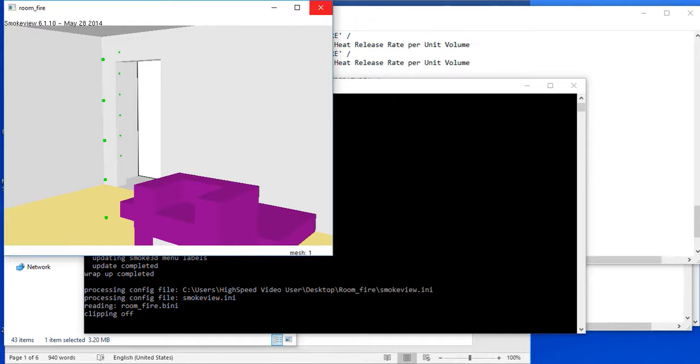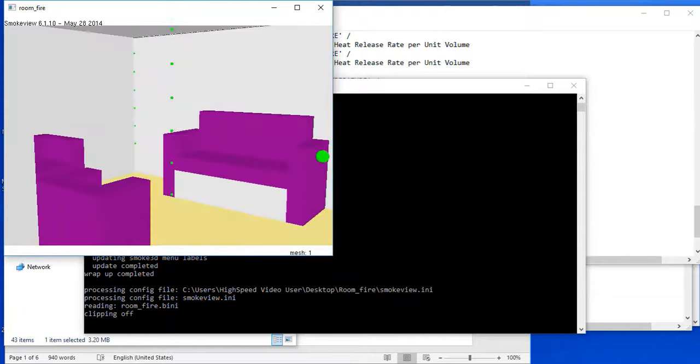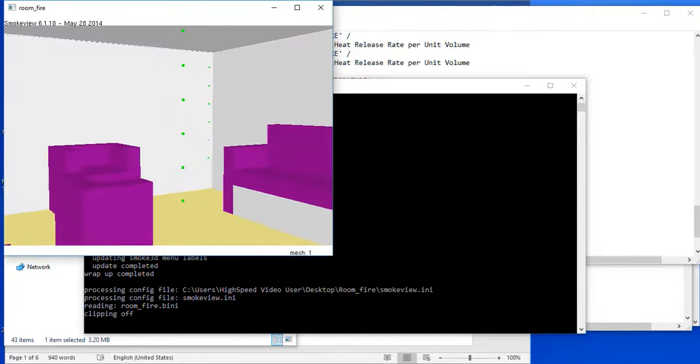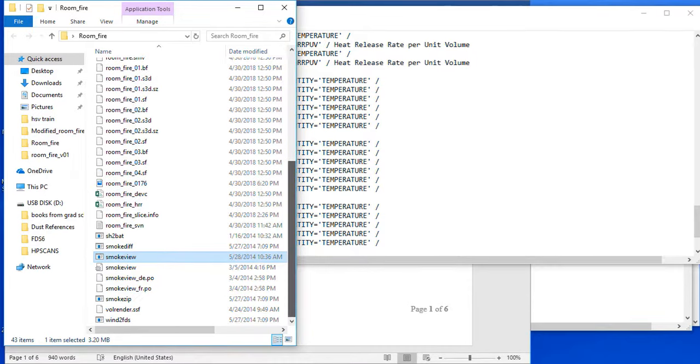So I used to assign a project where we had thermocouple tree data and a room fire and have people try to model it using the Nuclear Regulatory Commission's FDTs, the Fire Dynamics Tools, CFAST, and FDS, and compare what the students could get out of the different ways of modeling, the different levels of modeling, from a spreadsheet to a zone model to a field model, and write a report on the ease of use versus the data that you get out of it versus how well the model that was run actually matched the real experiment and the temperatures that were seen in the actual fire.